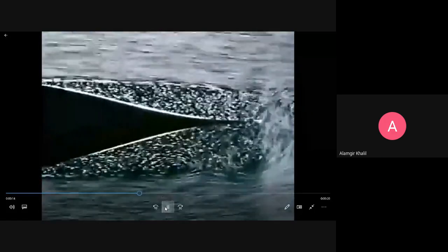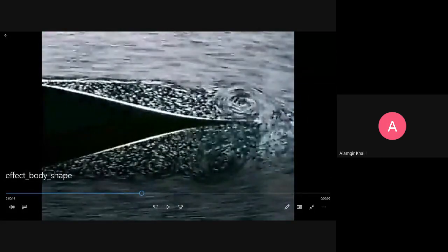For a flat plate, that's why the assumption is that the pressure gradient is zero. Because of that, there is no separation. But as we change to a more curved shape, you will see that separation will take place. Now we changed the shape, so you can see that flow separation takes place. In this case the flow separation has taken place, and there is a reverse flow. Clear? And what will be the effect of this? It will increase the drag force on the body. So this is an undesirable situation.